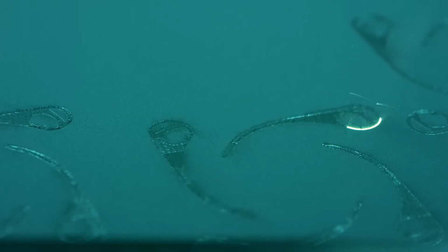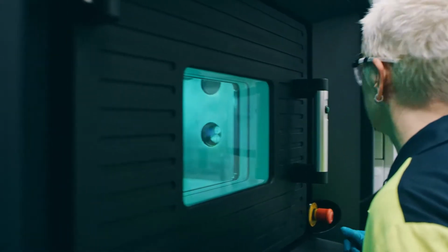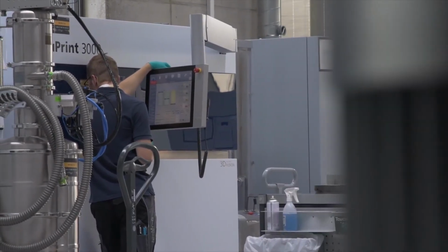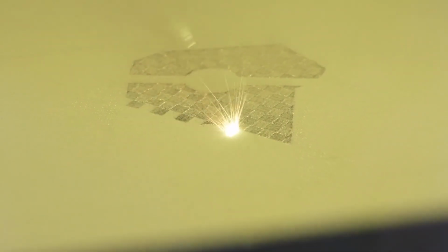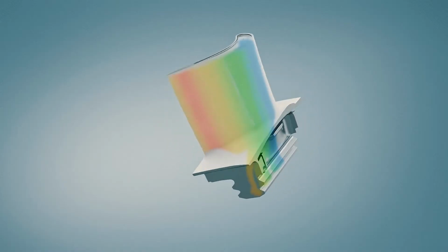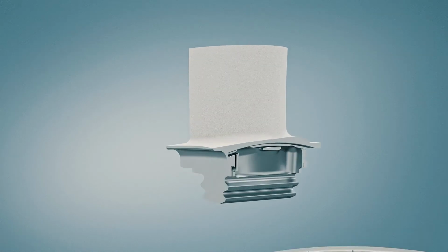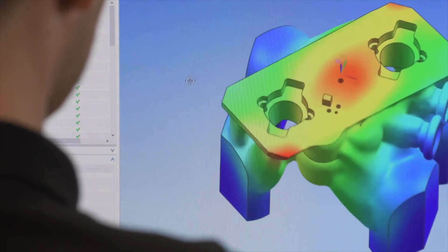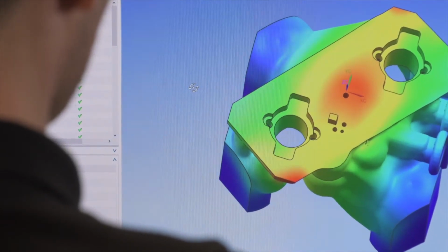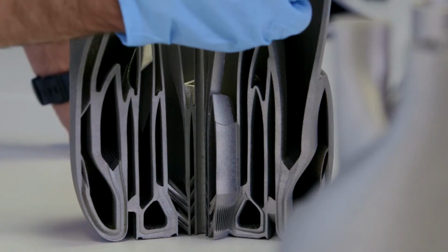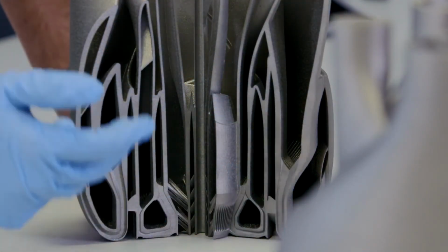In this demo, we refer to a production process based on additive manufacturing. The peculiarity of this technology is that to get the desired shape, the material powder is added instead of being removed, as happens in subtractive metal cutting based on milling and drilling. This allows us to overcome the cutter's access limitations and makes it possible to realize organic geometries. The resulting parts are lighter and stronger since we reduce the need for assembly.